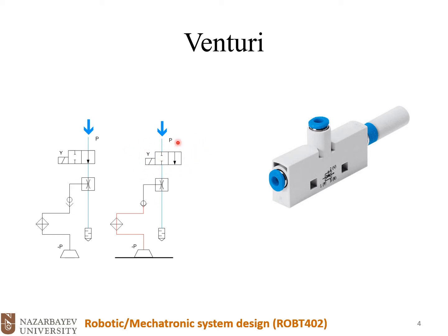So once the directional valve is closed, we don't have any airflow here, so we won't waste air to the atmosphere. Plus this line or the circuit is also closed and includes a negative pressure or vacuum pressure, and ideally we don't have any leakage of the air to the suction cup.